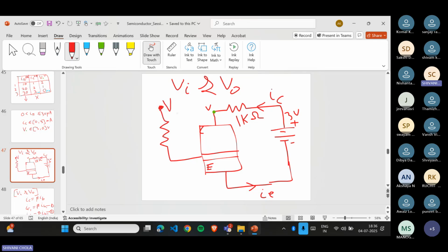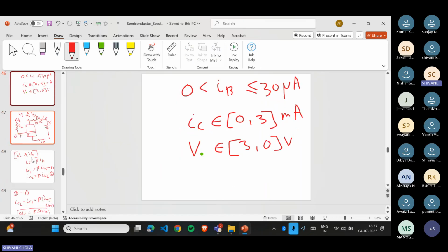And this we call as VI. Let's call this resistor RB, and this resistor RC. Is this clear? My intention was not to confuse you earlier, that's why I didn't mention the resistor. The potential at this point will be 0.7, even after this resistor, at any point on the wire. That's why in the earlier part, I didn't mention this resistor.